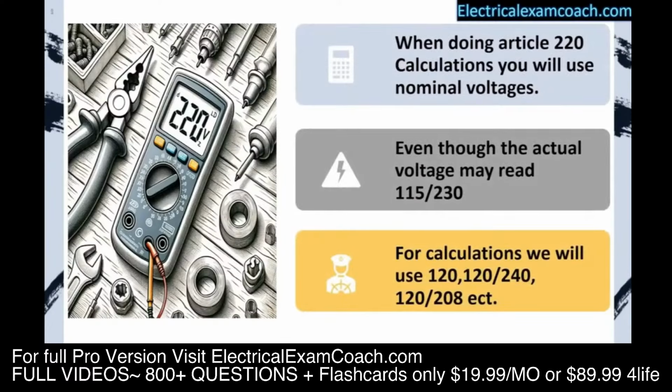When doing Article 220 load calculations, we're going to be using nominal voltages. Although our actual meter reading might be 115 or 130, for our calculations, we're going to be using nominal system voltages like 120, 240, 208. It makes it a lot easier to do these calculations, not having to guess or wonder what the actual voltage readings might be.